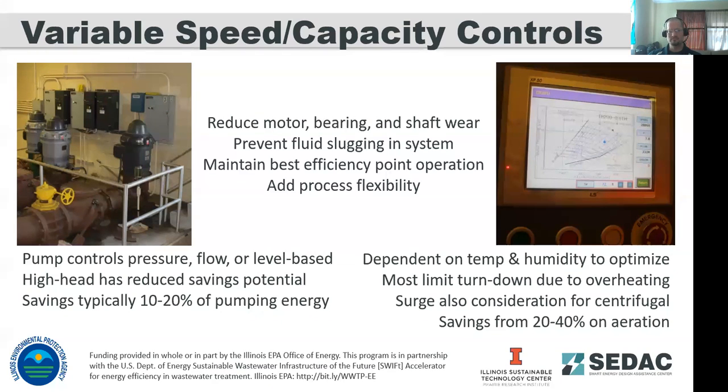Another consideration is fluid slugging through your system. If your pumps kick on and off, you get a sudden jump in flow rate through your process that sends a slug of influent into your process that can potentially disrupt momentarily your biological processes.